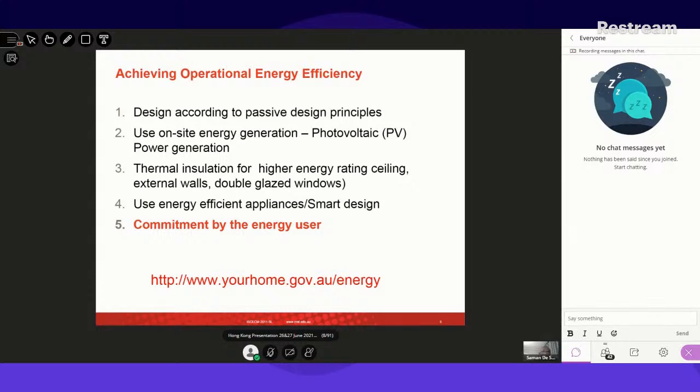But in the Hong Kong situation, one of the important things in house design is the cross ventilation aspect. If we can generate a draft on the cooler side of your house, and have doors, interior doors and windows aligned towards the warm side, then from one end it will suck air in at a lower level, and the heated air will rise up and exit through the louvers at another point.